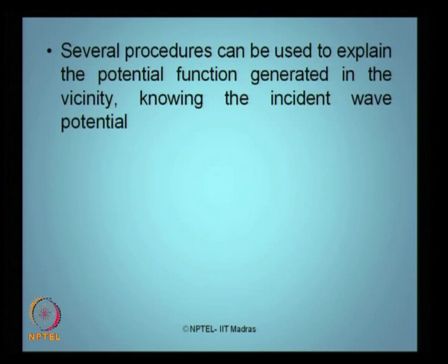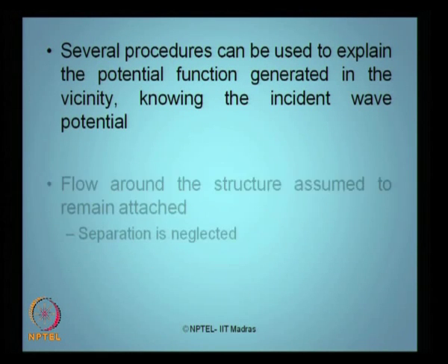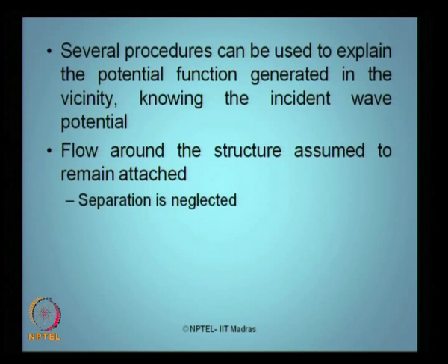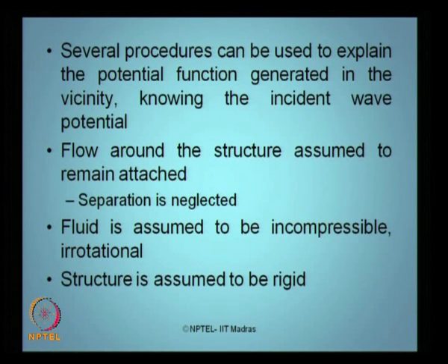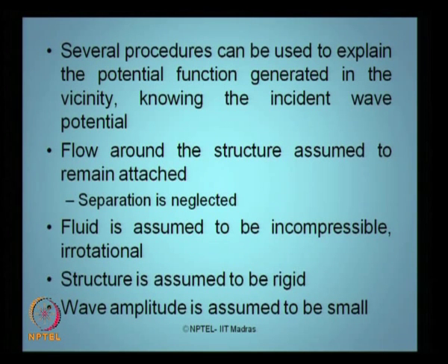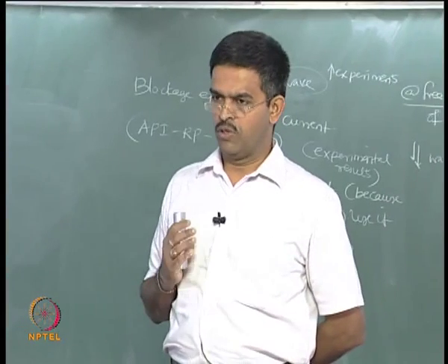Several procedures are used to explain the potential function generated in the vicinity if you know the incident wave potential. For example, flow around the structure is assumed to remain attached. I said it is a large structure, so the separation is neglected and the fluid is assumed to be incompressible and irrotational for our potential flow theory. The structure is also assumed to remain rigid, and of course we do this analysis only for small wave amplitudes.